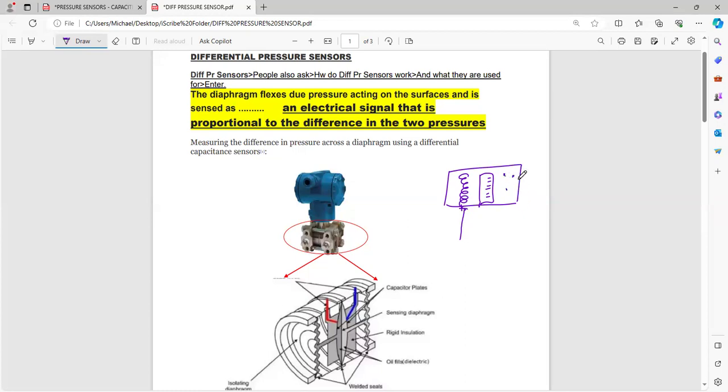I forget whether it's normally open or normally closed. Sir, is this arrangement for trip? For trip or even for alarm also. Otherwise, how are you going to have the alarm? Both. There is one for trip and one for your alarm. Check that.